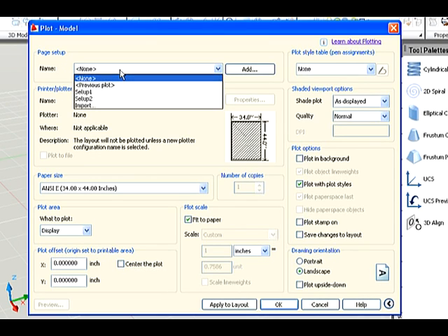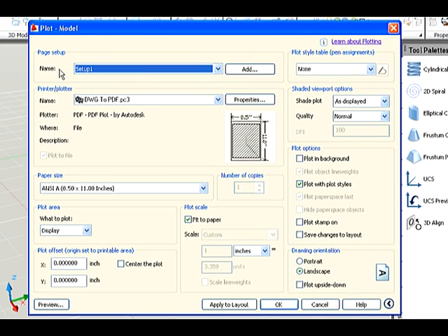From the Page Setup Manager, create or select an existing page setup to modify. The steps for each process vary slightly, but you end up in the Page Setup dialog box, where you can make the actual option selections. These selections define the characteristics of a page setup. The next one is a general overview of the types of options that are part of a page setup.